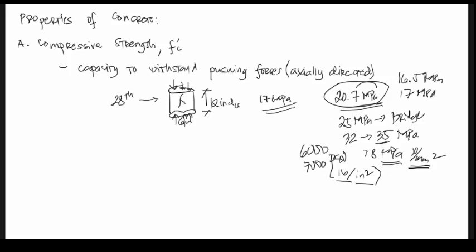Moreover pala, when you are testing, let's say for example, itong cylinder na ito, tinest natin at 28 days. May graph din yung compression machine na ibibigay sa'yo. I-graph niya yung stress-strain relationship. This is the stress, this is the strain from your theory of structure. Unti-untiin niyang lalagyan ng load kasi ito, yung cylinder. Hindi naman bibiglain na ikakrack lang, no? So habang tumataas yung load, tumataas din yung stress, no? Linearly. Hanggang sa umabot sa isang limit.